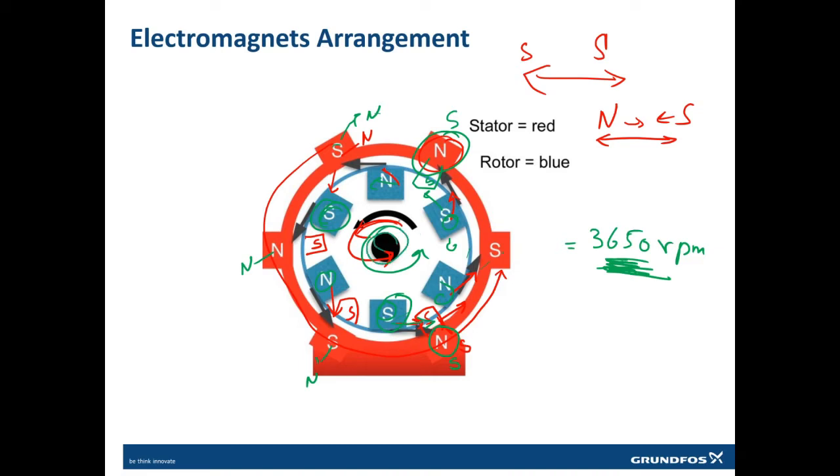And this rotor is free to move. You can easily rotate it with your hand. Because of this very low friction, this magnetic field rotating around the rotor will attract the rotor along with it. So this is called induction. This is called the squirrel cage induction motor. But how are these different parts working? Now the question is how I am able to change this south to north and north to south.